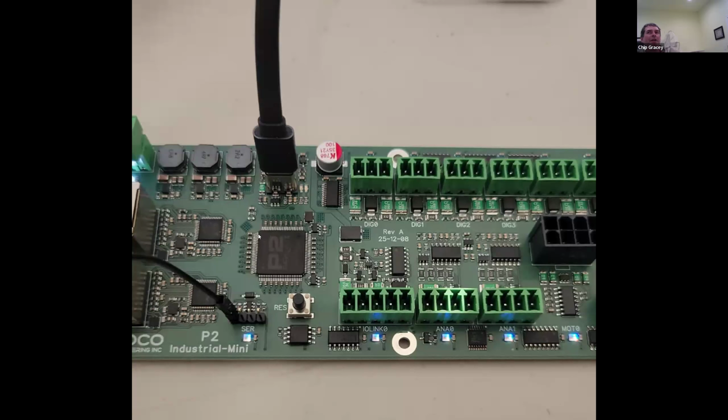So if we're ever going to resurrect that board, we need to replace the P2 and the H-bridge, but that is a really messy proposition because you have to get so much heat to get that tab off of the P2 that you're probably going to melt the switch, you're going to melt these connectors. There's going to be a lot of melted stuff afterwards. And, yeah, that'd be a situation where having that industrial P2 device would help. You just pop it out, pop it back in. Yes. Back in the game.